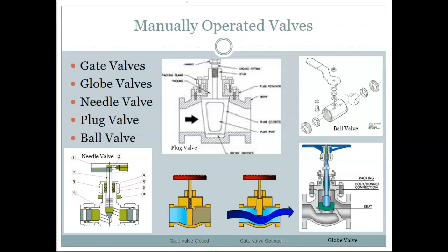Y'all were using one, actually, I'll take that back. Y'all were using 2 the other day in lab. You have the one above your head that you pull open, or push open rather. What does that do? It allows airflow, right? The other one is on your actual trainer. It's that little blue switch on your air source, where you flip it one way and it allows air into your whole system. You flip it the other way, closes it off, you can't get any air, right? Those are manual operators. Another example, push buttons. You get to push the button or you flip the switch. That's manual operation.